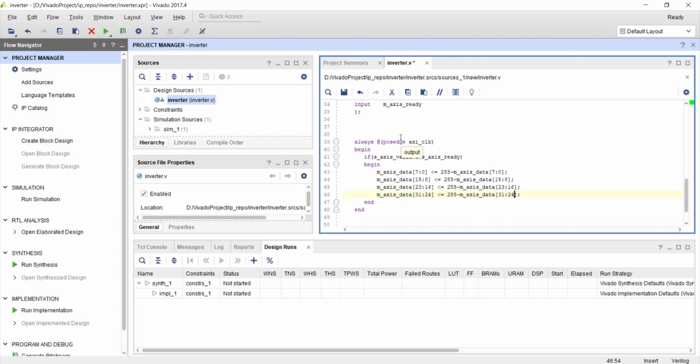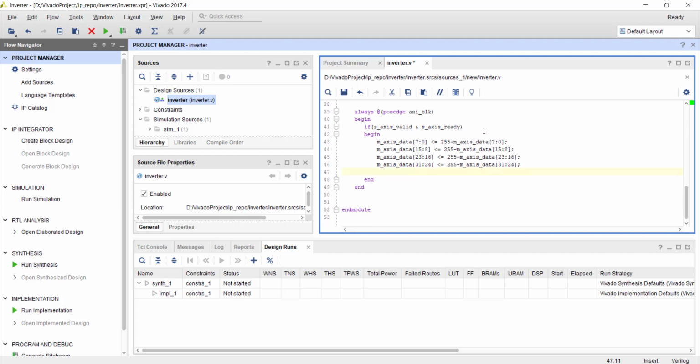Now if you are parameterizing it, we need to write a general case. So I will use a for loop in this case. You haven't seen a for loop in synthesizable Verilog code before, so we won't make a blanket statement like you cannot synthesize or implement a for loop or while loop in Verilog. You may or may not be able to implement a for loop depending upon the coding style and for what purpose you are using it. So let me try something like this.